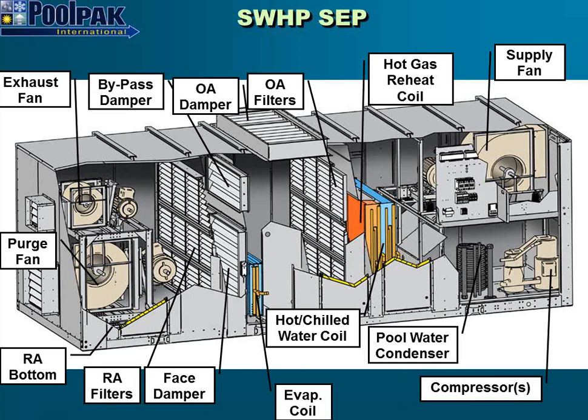Another purpose for using the purge fan prior to swim meets, prior to events, if you just want to freshen the air. Some pool managers use this, say, every 24 hours just to bring fresh air into the pool area. Caution here, of course, we suffer pretty severe winters up here. When you're purging, make sure that you have enough auxiliary heat to maintain control of the building.